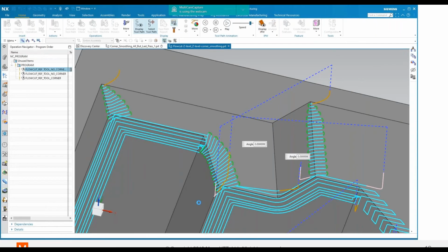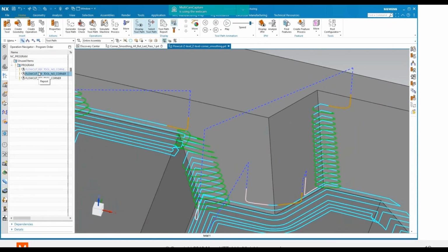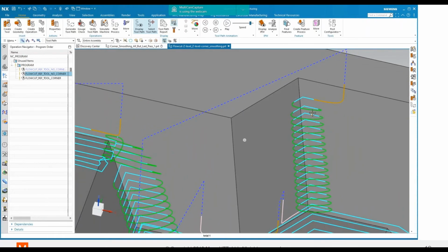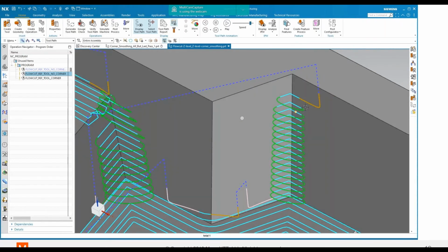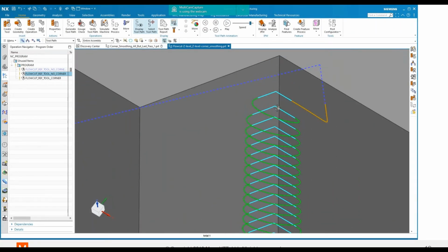So let's look at another set of operation parameters that would solve that. This is the same command, it's still flow cut, but we've just adjusted a few things. And now we're always climb cutting, and we're doing the smooth transition back to the beginning again. A really nice toolpath. Okay, one final thing though that we might want to change is the fact that we've got a tool that can fit completely into our corner here. In other words, I don't have a fillet designated here that has a larger radius than my tool radius, so I do see the sharp 90-degree corner.